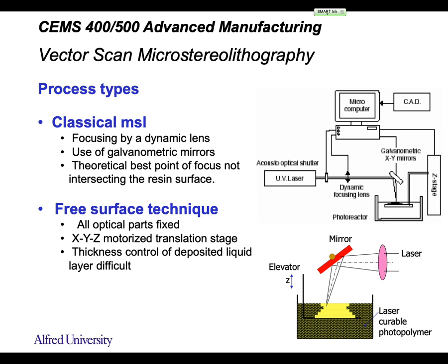But there also will be some other problems, right? Because of the resin, it's a low viscosity resin. If you move the resin in the XY direction really fast, the surface will not be flat, right? So there will be some trade-offs. You may have to print at a pretty low speed.